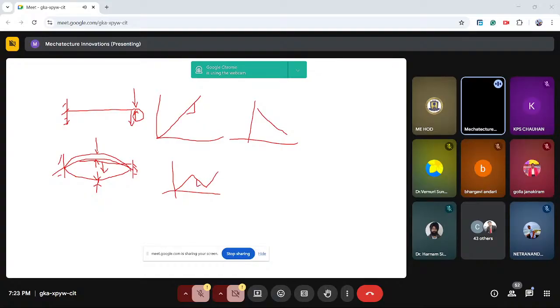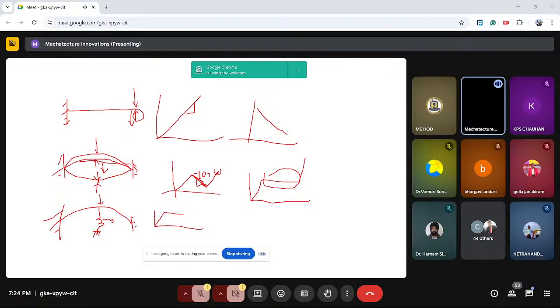So this negative stiffness region comes because my object snaps from one stable state to another stable state. Now I want to make a QZS. For example, if this negative stiffness is minus 10, I want to make a zero stiffness region by adding a positive 10. So how is it done physically? This is the arch, and to the arch there is a spring. Assume the stiffness of the spring is exactly the same as the negative slope. When I apply force, the force-displacement curve of an arch supported by a spring at the middle will be positive, then zero stiffness, then positive.